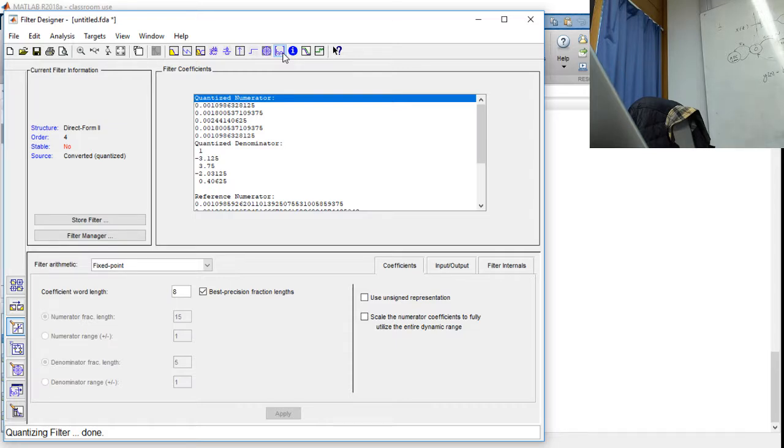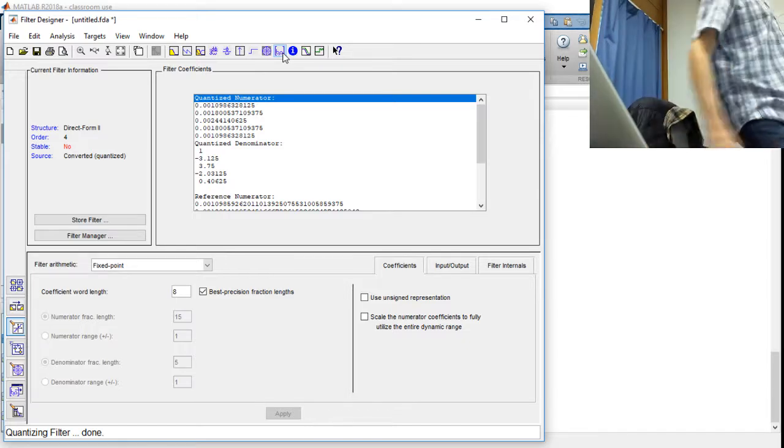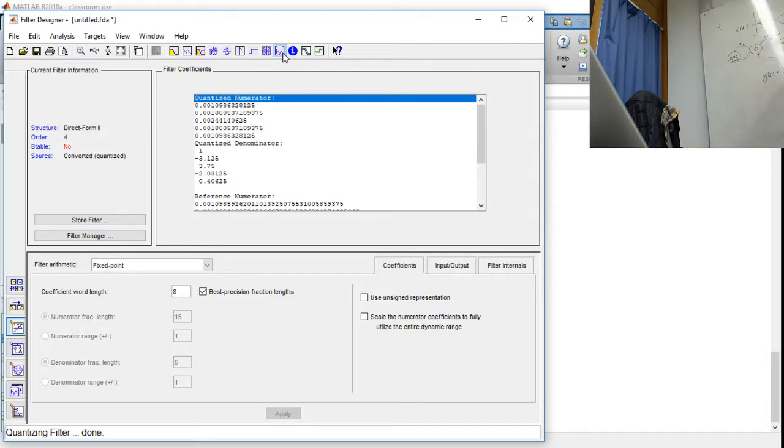If we go into even higher degree systems, we would get even more difference on those numbers when we have a single section. But on second order sections, we have basically optimal calculation accuracy. So if possible, do the calculations on second order sections, especially on IIR. The IIR denominator fundamentally dictates the performance of the IIR system.